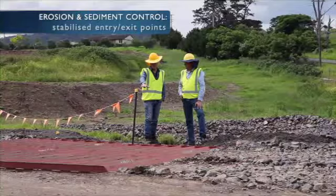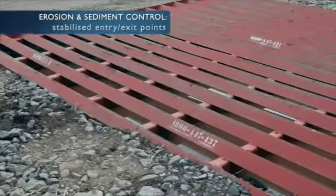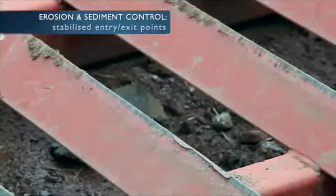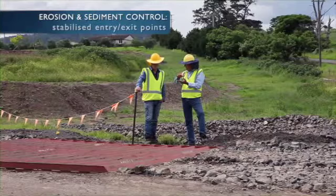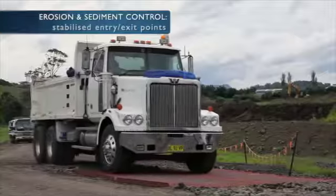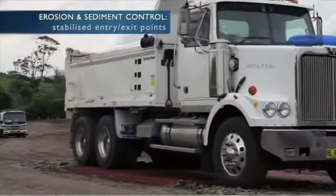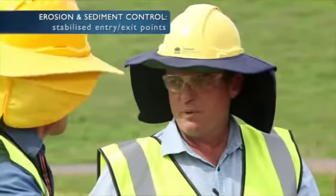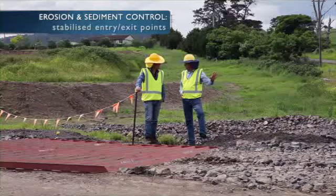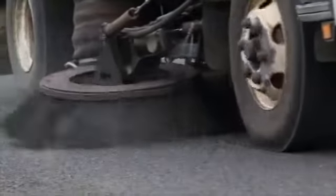Now, this looks like some sort of cattle grid. Yeah, it does, Pete, but it's actually a designed shaker grid. You'll see that it's got the pointy tops rather than just the standard flat tops that a cattle grid would have. And that helps to actually further agitate the truck or the tyres as it goes across and remove more mud. But even using these controls mightn't be effective in really wet periods, and we may still get that mud tracking out on the road. So often we'll have to revert to a street sweeper to actually keep the road clean.